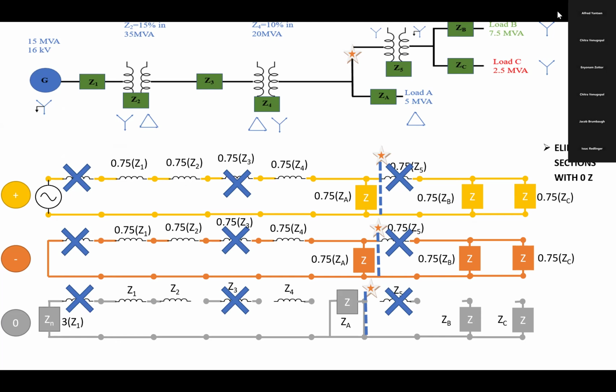So positive sequence, negative sequence, the load, just connect everything and then solve the network. This is where the fault happens. So before the fault, how the circuit behaves, and after the fault, how it behaves. Before the fault, this circuit is going to go empty, and only this side is going to exist.